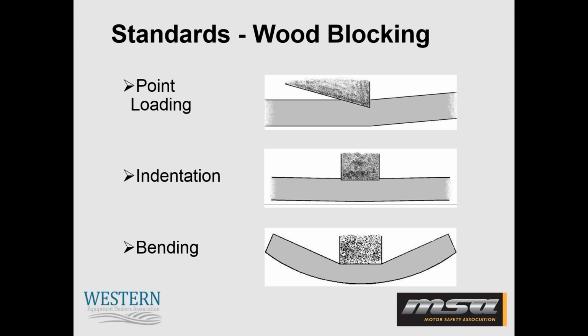It's going to carry a load with little deformation right up until the point of failure, and it doesn't give you any of those creaking noises until all of a sudden it fails. It may splinter or fail quite suddenly. So just be aware of extreme wetness and extreme dryness of blocks because they are going to cause different situations that you need to be aware of.